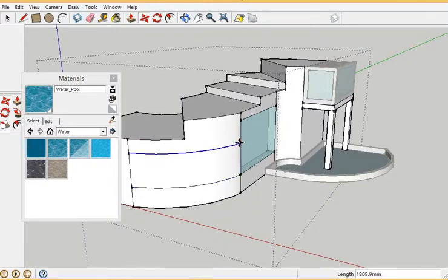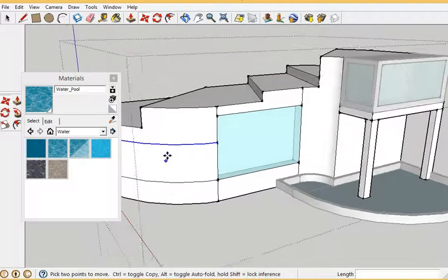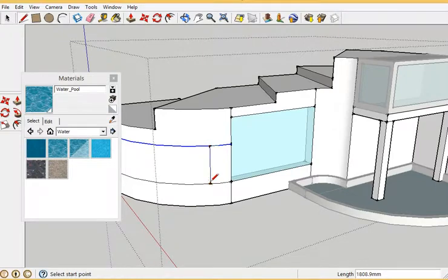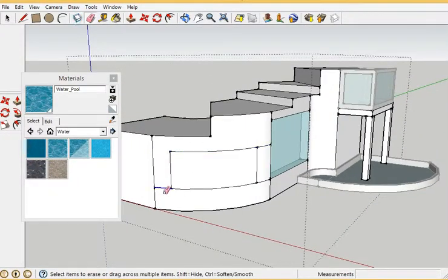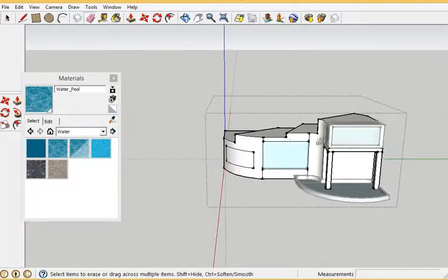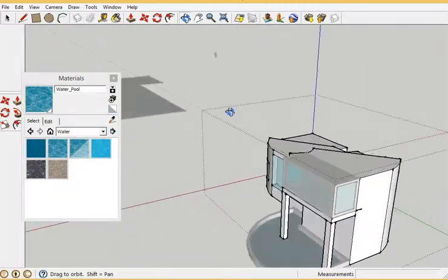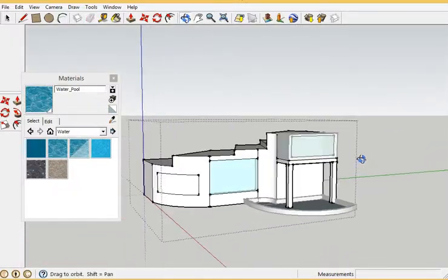Now, to activate the tool, you need 2 clicks to start. 1 click sets up the pivot point. So we can see which axis I want to rotate about. Well, I'm going to go somewhere around the center here. And now I can actually start to rotate. And notice how SketchUp Pro will tell you how to do that, and it's rotating around that pivot point I set. SketchUp of course really is just how to use it.